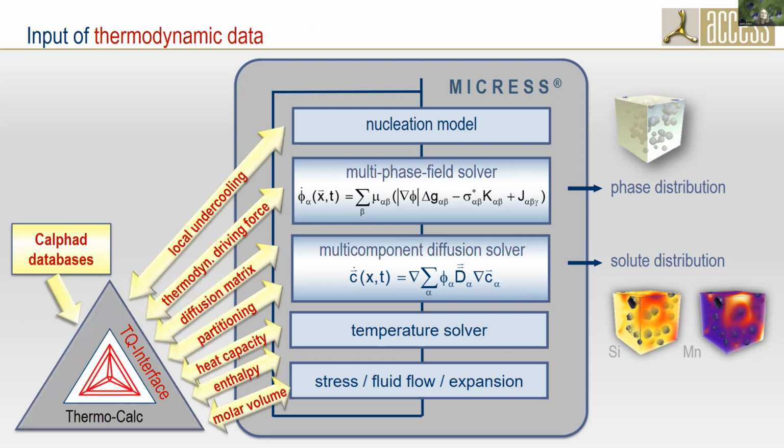So of course, we need input data for the model, and an outstanding feature of our software is the direct coupling to the thermodynamic interface, to the TQ interface of the Thermo-Calc software. This means we can directly evaluate CALPHAD data during the simulation, which gives us a very accurate description of multi-phase, multi-component systems.